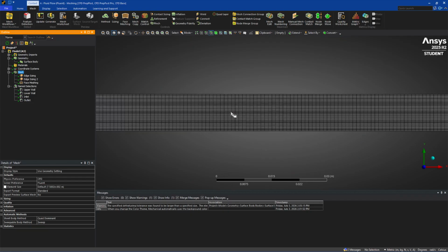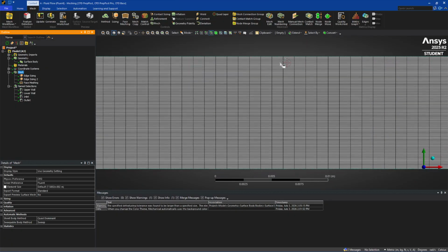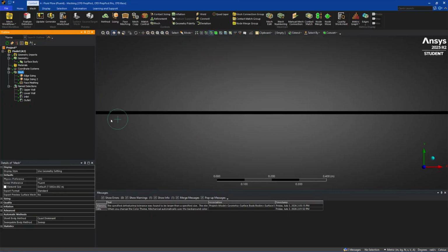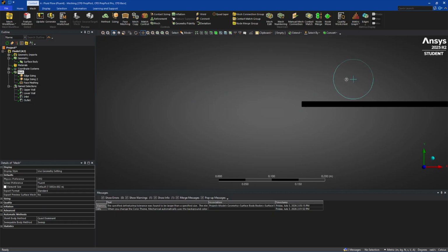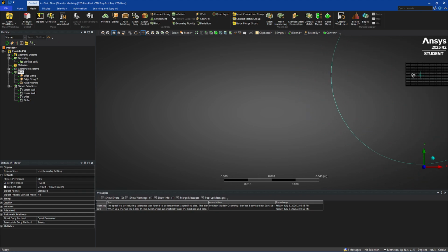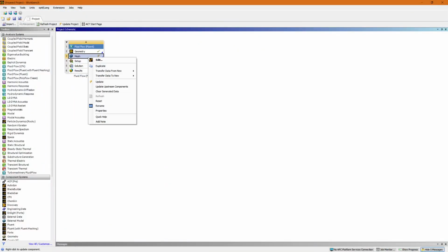Verify that mesh should be nice and dark up until you get really close. So I've got a super fine mesh on this, which looks about right. And then just to verify, my endpoints should be a little bit more fine than the rest. Just check that down here. Let's see. Whoa, what did it do? There we go. Yep, perfect. Alright, so that's the mesh complete. And go ahead and update this. And now we can go right in the setup.